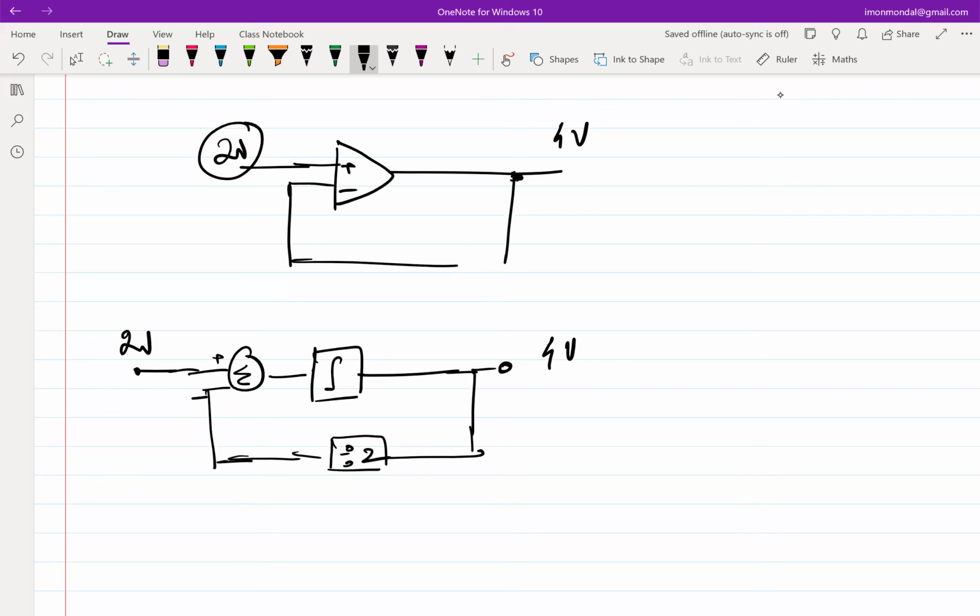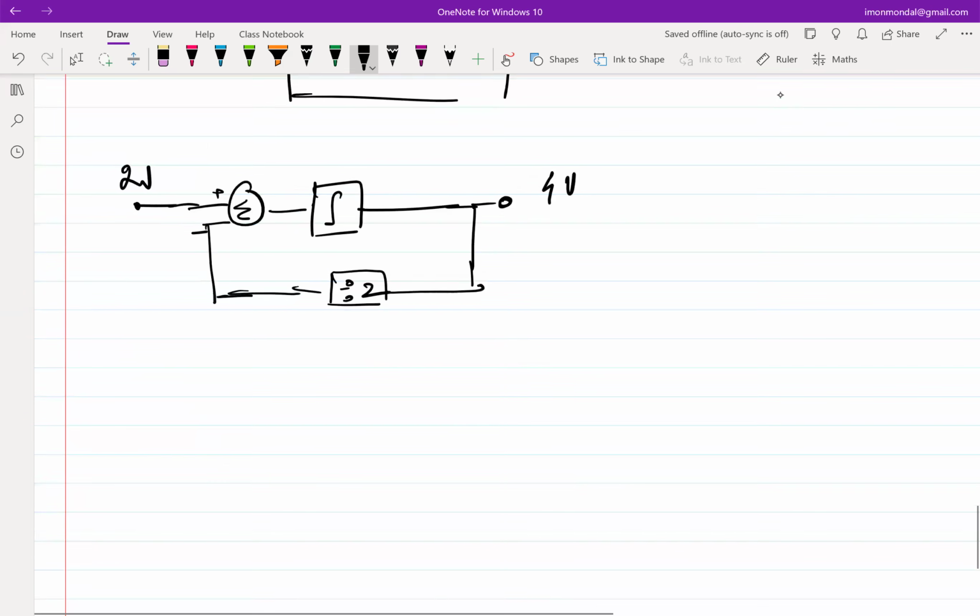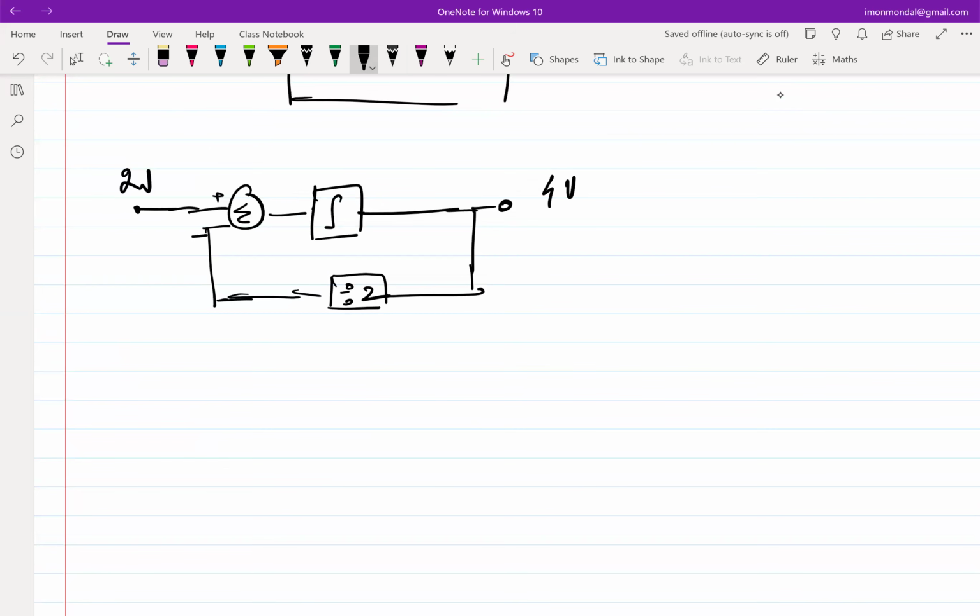So if I use the same philosophy to design a stable on-chip reference, I would need an input, which is a crystal. This is a crystal, which is a stable reference, which gives me some sort of very accurate sinusoid. It gives me some frequency. Let me call it a sinusoid: Vp sine omega_ref t, or 2 pi f_ref t, where f_ref is extremely stable, no change. Let's assume no change.